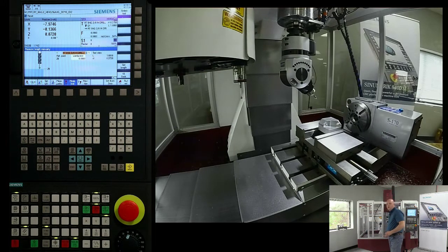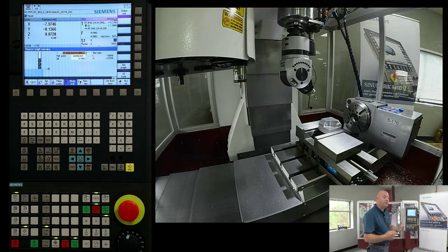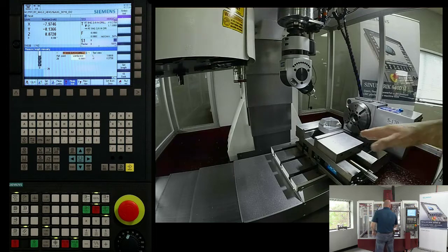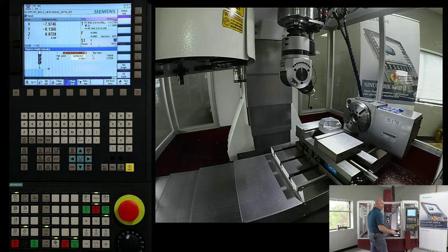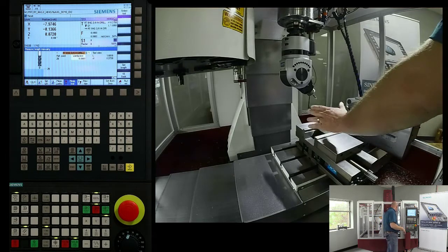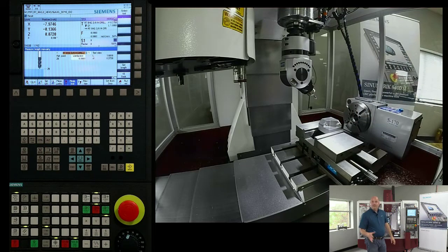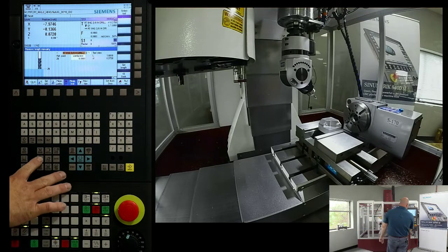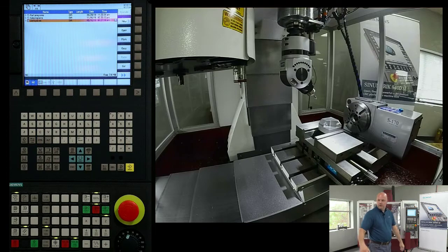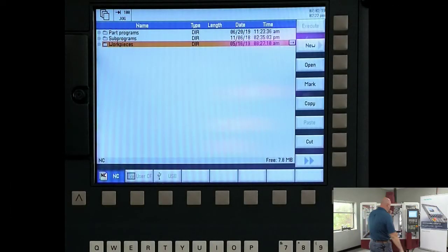Okay, so our next step is to show you how I can apply this in a real-world example, in a part program example. The part you see here, this little cutaway, has these orientation angles, and we're going to show you the operations that do the drilling orientation. I'm actually doing a little bit more than just drilling. Previously, I milled all these surfaces with the head at the 45-degree planes and the compound 45-degree plane. Then I took another tool to relieve it out so we could see what's happening internally. From a programming perspective, we'll zoom in here a little bit for you, to make it a little easier to see.